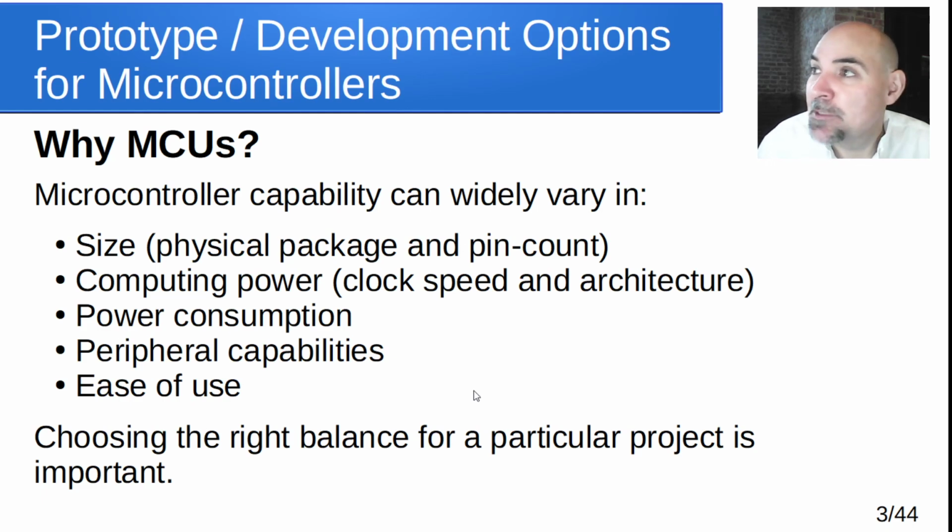And then there's also power consumption. If you're making something that's battery powered, clearly long battery life is advantageous. So you might use something that has low power consumption compared to something that has to be very quick and responsive and is going to be plugged in rather than running off of a battery. It might not be as important if you're plugging it in as if it's running off of a battery to save power. So there's a balance between a lot of these different features, including cost, what peripherals there are, and how easy it is to use. Choosing that balance of cost versus performance versus your project's needs versus how much power, finding the right microcontroller for the right application becomes very important at that point.